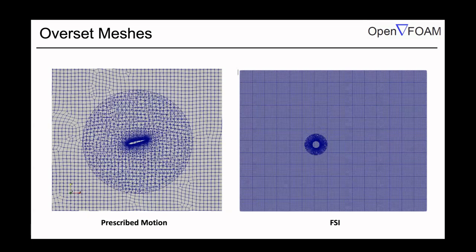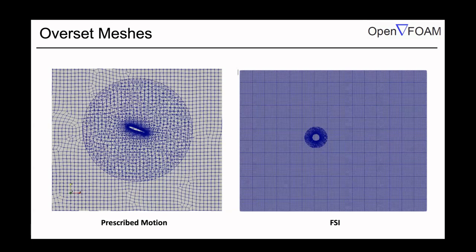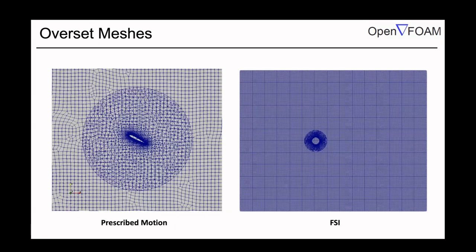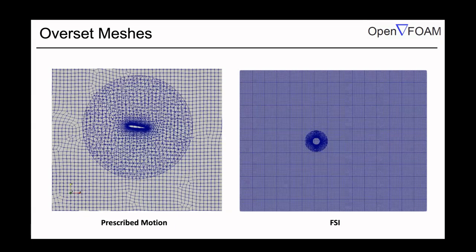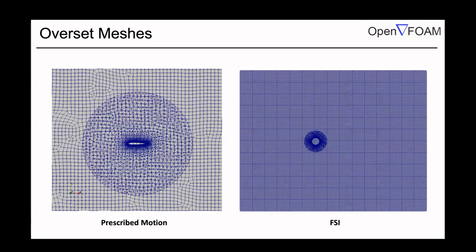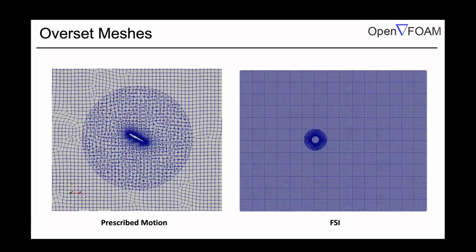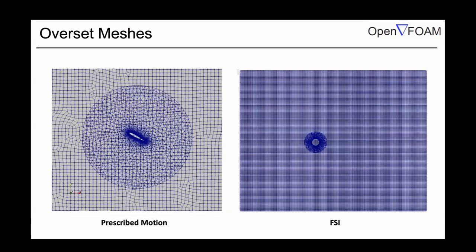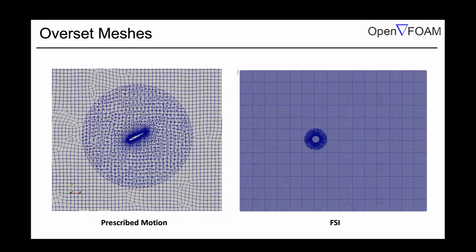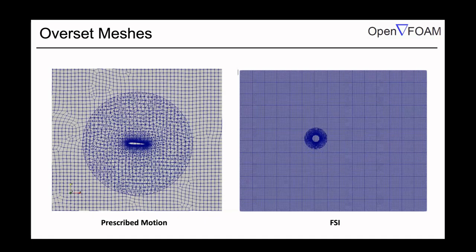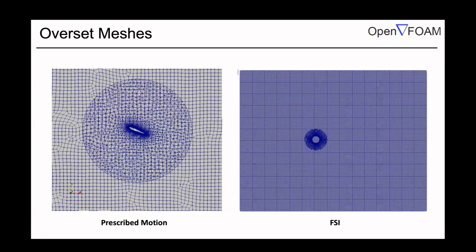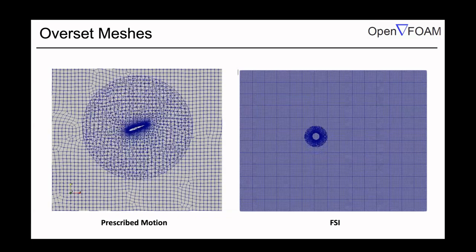So even if it looks very lucrative, unless we really need it, I don't want to use the overset method because it is always less accurate compared to the arbitrary Lagrangian-Eulerian method. And the 6 degree of freedom component is exactly the same as I have shown you for the morphing method. So we need the structural parameters, mass ratio, inertia, everything, and then we need a structural solver to couple the structural displacement into the Navier-Stokes equation.